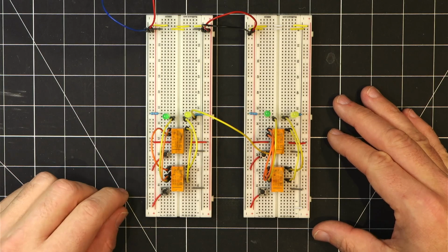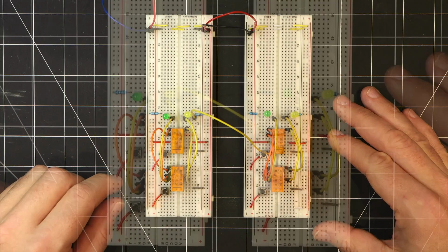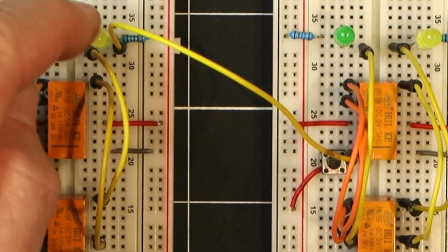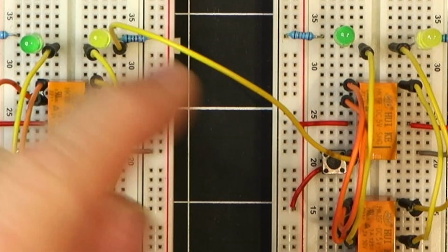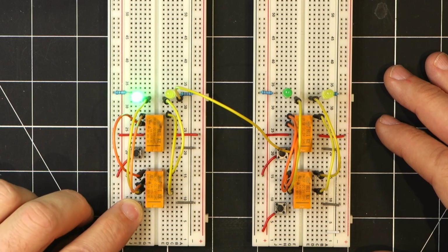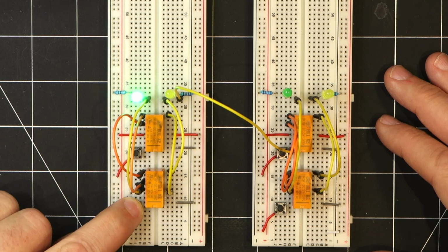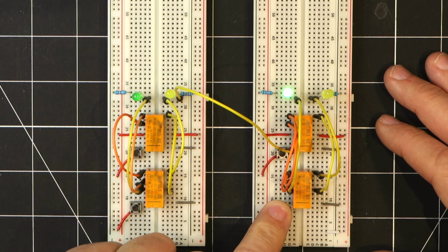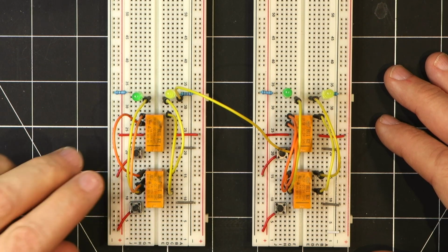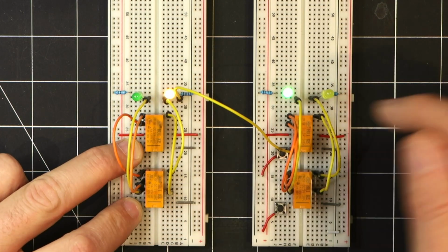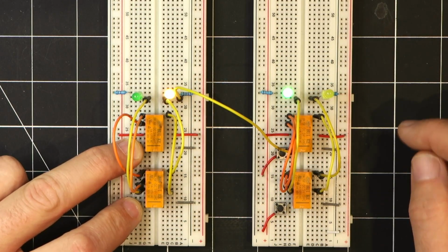So this is a quick demonstration of the ripple carry effect between half adders. These are 2 identical half adder circuits, and what I've done is tied the carry out from the first half adder to one of the inputs on the second half adder. And when I select the A input, you'll see that we get the expected sum value in the first half adder. And if I select the A input on the second half adder, you'll see that you have the same effect. Now, if I select A and B, we have the carry out being activated, which now activates the input on the second half adder.